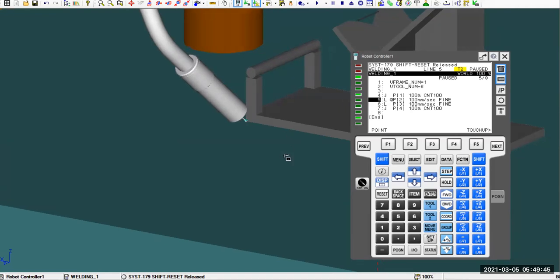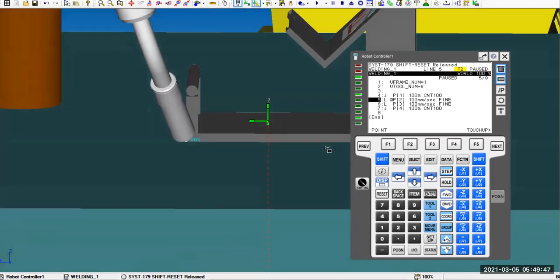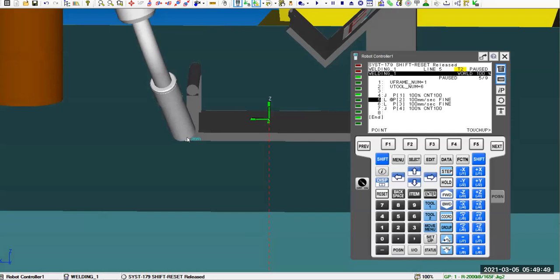And also, if I rotate this way, there's supposed to be some sort of angle. So you can see here, I can draw the line here. If you draw the line here, right, sorry, that's not straight. So if you have a line here, you're welding on here, supposed to have, maybe check on the internet, lots of welding experts mentioned that it's supposed to be a 12 to 15 degree angle on here, right?